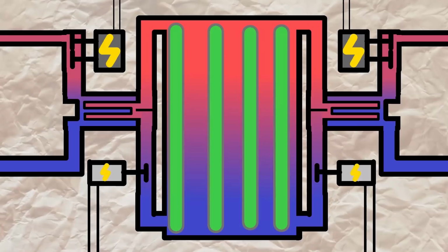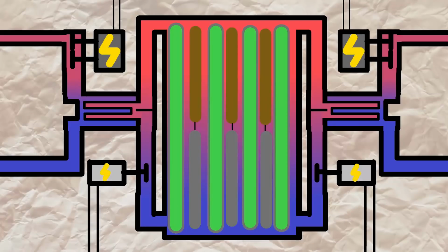The neutrons themselves move too quickly to actually hit an atom, so you slow them down using water and graphite. The water then heats up and it goes to drive the turbine. Of course, the water is radioactive since it comes right from the core, so you don't actually use this water for the turbine. Instead, you send it through a cooling loop. That means it cools down and heats a completely separate water loop, which then becomes steam and turns the turbine. This way, the radioactive water is in a closed loop, so it can't leave the reactor and irradiate things.